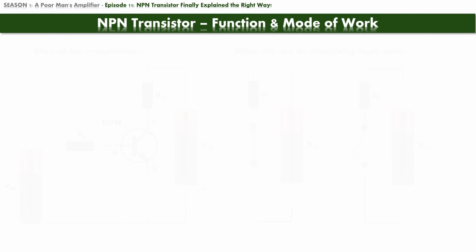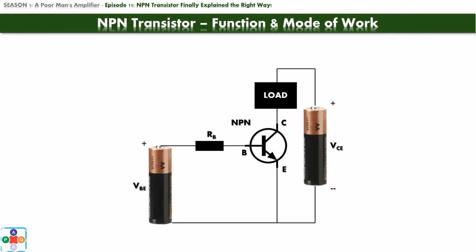That something we are turning on or off in a transistor circuit is called the load. That is just a fancy name for anything we connect between the power source and the collector terminal. Next question is, where does that switching on and off current come from? Well, it comes from something called signal generators, if we want periodical switching, or it can come from photodiodes. The mechanism of every door that automatically opens when you approach it consists of some sort of diode that senses your presence, and a transistor that switches on and opens the door via some internal mechanism. Transistors in a role of switch are everywhere around us, even if we don't see them in plain sight.